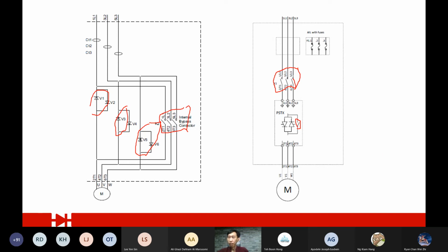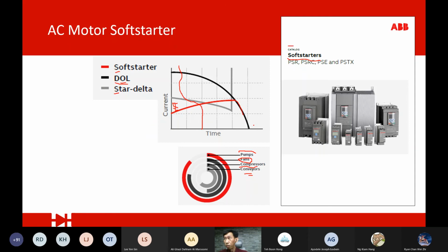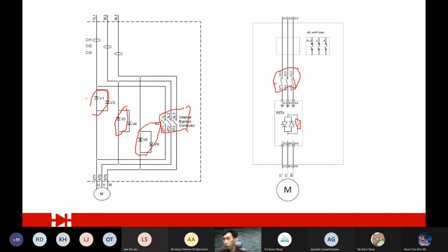So then we are done with the AC controller that controls the magnitude of the AC. I also showed the real application commonly used in this. If one day you happen to work on a soft starter, when one of the phases is unbalanced, usually one set of these is already spoiled. You can change the part, and you can design your own soft starter.